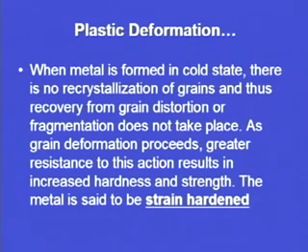As grain deformation proceeds, greater resistance to this action results in increased hardness and strength. The metal is said to be strain hardened. So, hardness and strength increase, and the metal is said to be strain hardened.